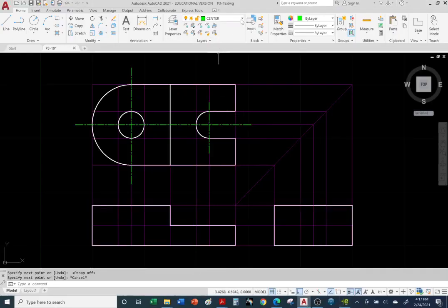Okay, so let's draw some red hidden lines. Go to the hidden layer, use the line command. And I know it's supposed to line up with this quadrant. Let me turn on Object Snap again. And see, that's where I want to go off of, that left quadrant. So I can just track down, yep, and this is where it starts.